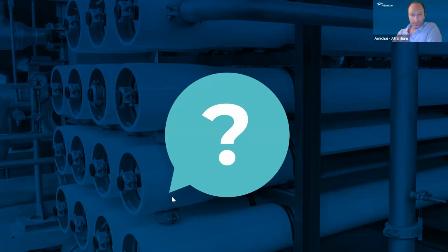Additional questions? Just a minute. What considerations should we keep in mind when selecting and implementing UV systems for this purpose? I'm assuming dechlorination in general. We talked about the water quality parameters when doing sizing. When doing maintenance, and the maintenance here is very, very low, basically it's a lamp change out every 6 months or more. I would advise operators to have extra lamps on site, some O-rings if needed, but these are the spare parts that are needed on site. Again, the maintenance is very low on this system.